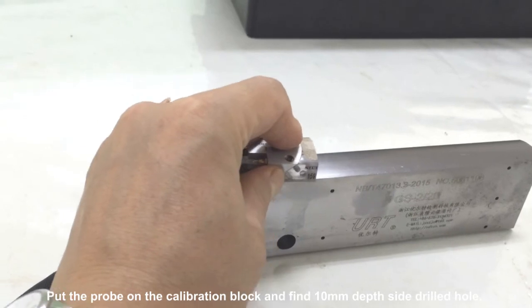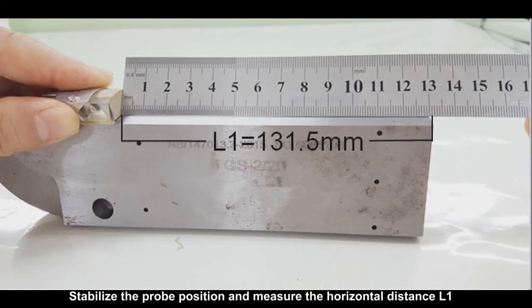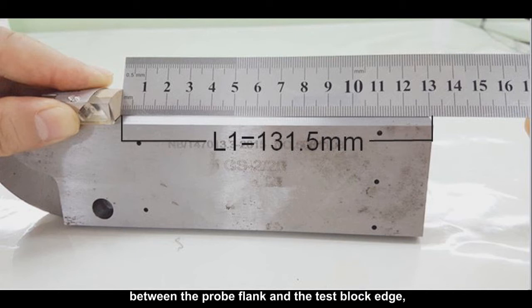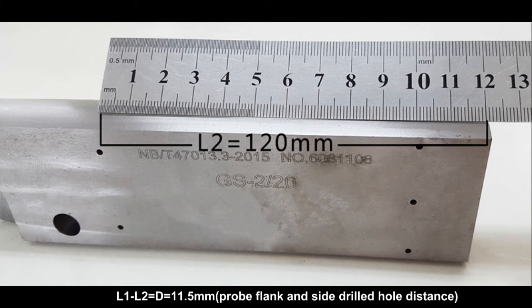Put the probe on the calibration block and find the 10 mm depth side drill hole. Stabilize the probe position and measure the horizontal distance L1 between the probe flank and the test block edge, and L2 between the side drill hole and the test block edge. L1 minus L2 equals D, the distance between the probe flank and the side drill hole.